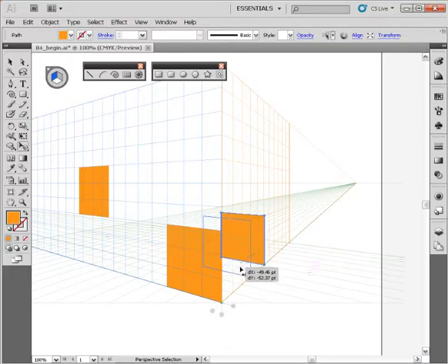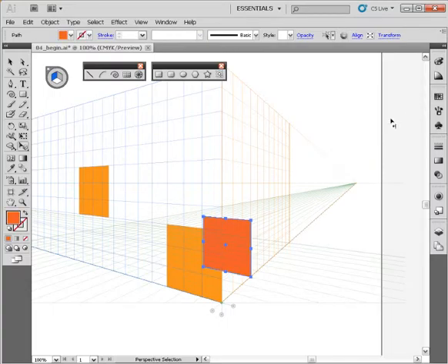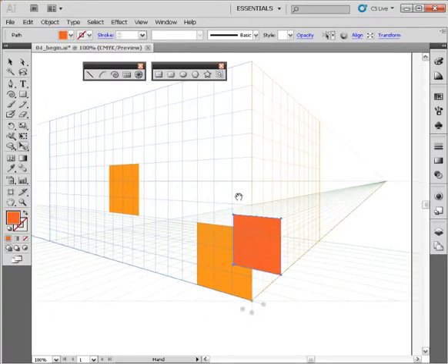because I want to show you a potential problem. This is where Illustrator falls short of 3D applications. Let me change the color of that object. You can see here that while we were able to create a sense of depth by creating that copy perpendicular from the original, Illustrator doesn't really understand the stacking order and how that should be affected by that copy. So Illustrator still thinks this one is on top. So we actually have to change that stacking order.